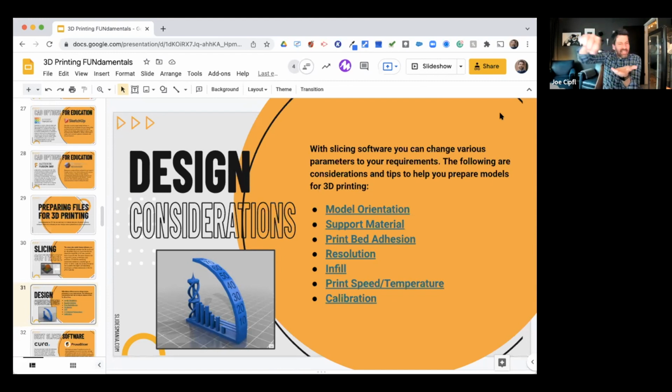If I'm seeing visible layers in the print, or maybe a shift in the layers, maybe it's not adhering down quite as strongly as it needs to, and so I have to move my nozzle down for the calibration. So again, you've got default settings, use those default settings.